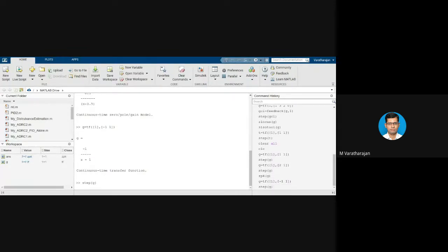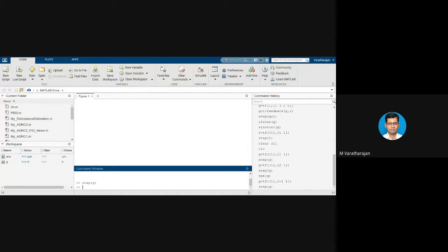Okay. Let us see the step response of the system. And if you have a negative time constant, then the system is not at all settling. Okay. I do not know whether you are able to see this value. The y-axis is in the magnitude of 10 power 25. Even there it is exponentially rising in the negative direction. That means system is completely unstable. Okay. The pole position determines the stability of the system. Also, it determines the speed of response of the system. The first task you are going to do this.